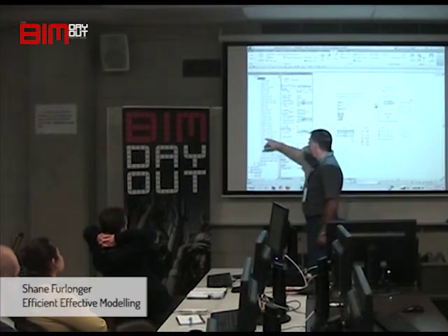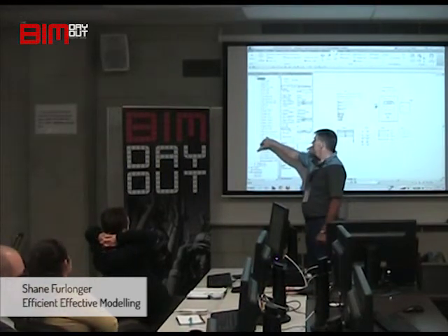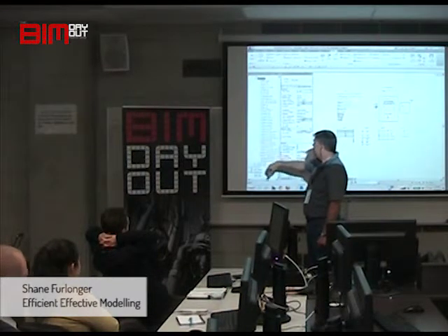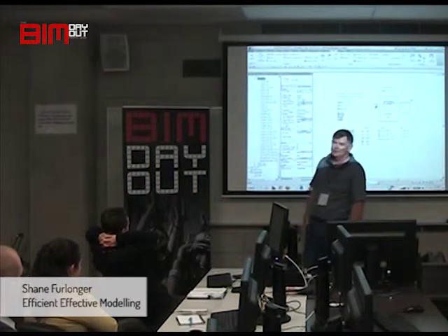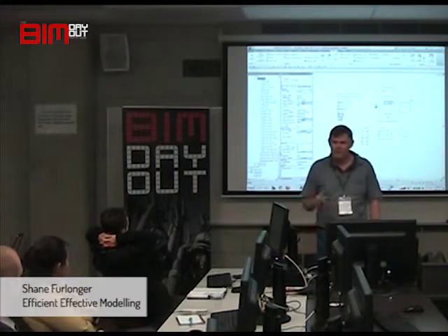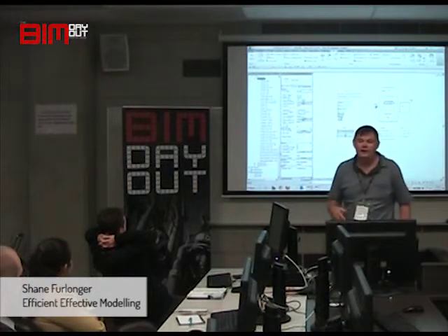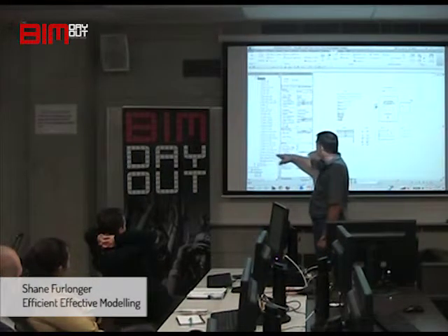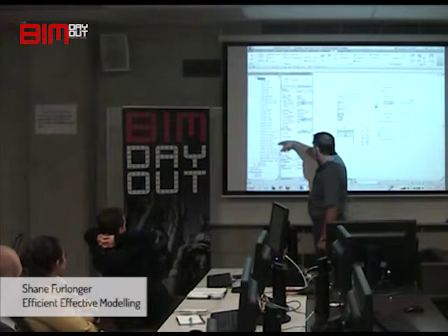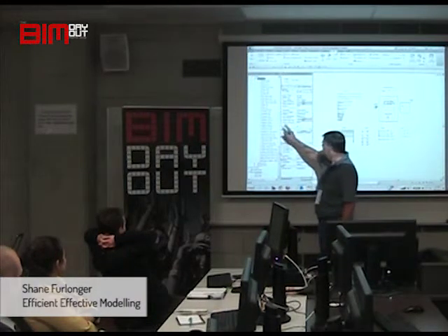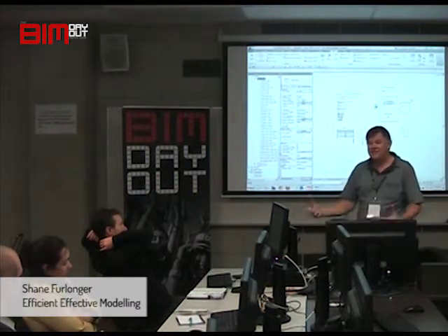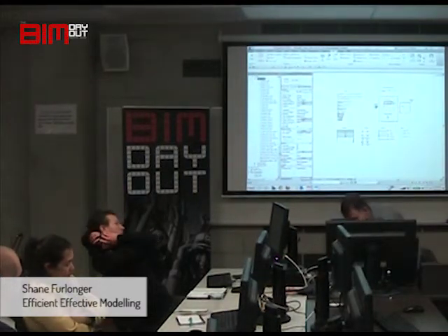So these are all stud walls. P for plasterboard, S for stud, or steel stud, and P for plasterboard again. You might think, what the hell is a V? But V for villa board. I know it's a brand name, but it was easier than typing in CFC, which I've got in here somewhere, I think. No, maybe not on that one. I've had to use CFC. But villa board, just a V, stands out when you're reading it.